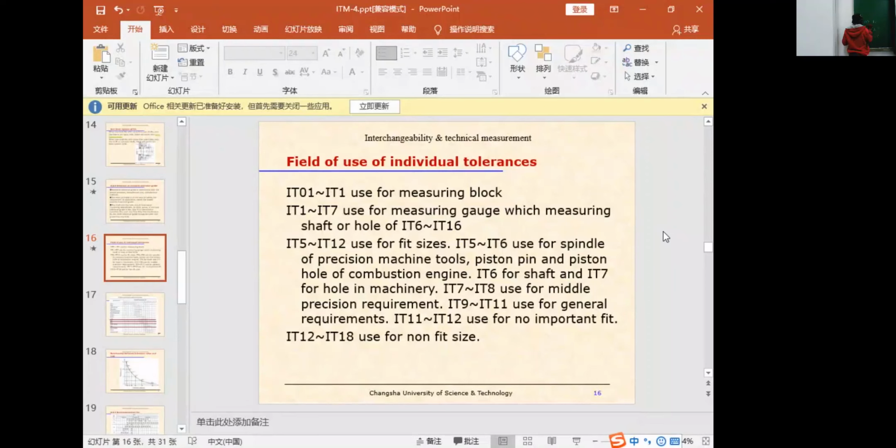And then this is the shaft. Usually we lower it by one grade, so it's 6. Yes, usually one grade. In machining we lower here. We still add the delta when we are designing the hole.